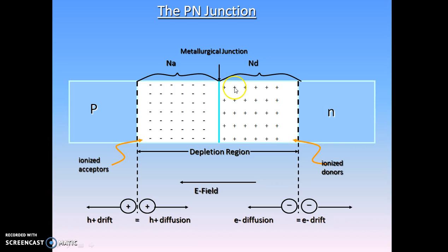The depletion region includes the net positively and negatively charged regions, and this region does not have any free carriers. Now Na and Nd represent the amount of negative and positive doping in number of carriers per centimeter cubed. These occur when no external source is connected to the p-n junction, or in steady state condition. So diffusion and drift balance each other for both holes and electrons.